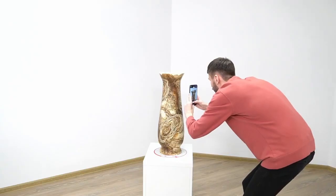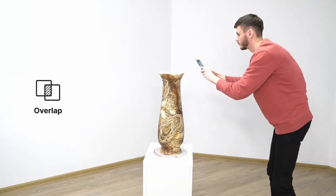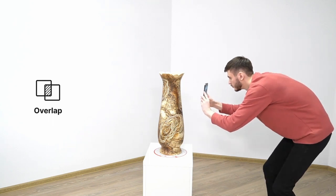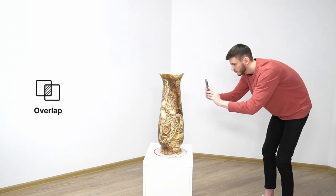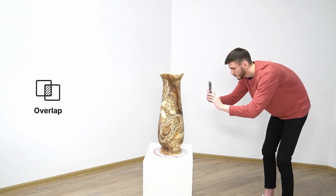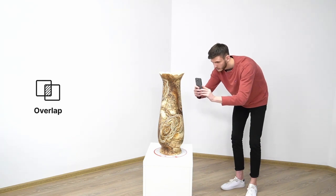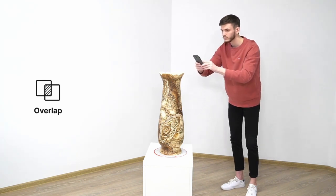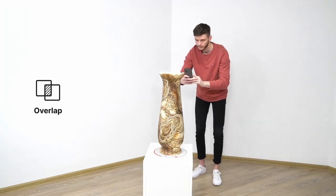Okay, now let's begin taking pictures of the vase and point out some more important aspects. Overlap. When moving the camera, we should establish a significant overlap between the shots. A 70% overlap is something you should aim for. To make sure we have enough info for registration, each element of the object should be photographed at least 3 times. Please avoid taking pictures of any additional object that can disturb the texture. And basically just take the pictures of the object that you're scanning and nothing else.